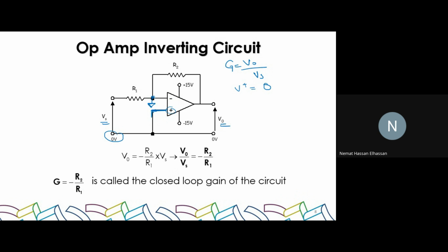That's the first scenario. The first rule of the ideal op-amp gives us a virtual ground, so V positive equals 0 equals V negative. The second rule is I positive is equal to I negative, equal to what? 0 amperes, which means the current here is 0. There is no current passing here, as if there's no connection. Keeping this in mind, now let us look at this branch.